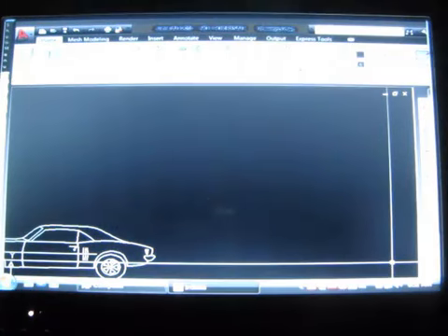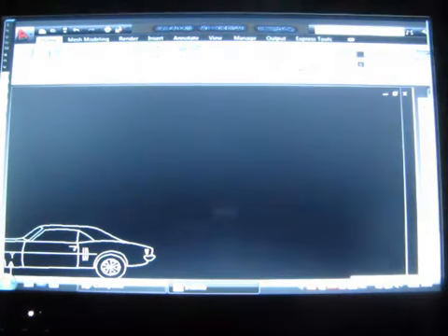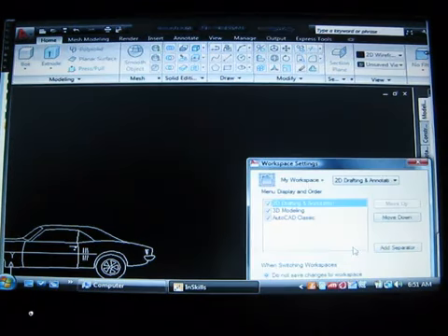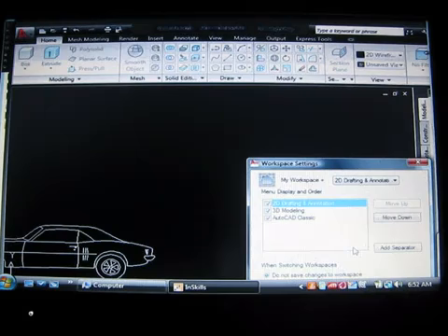There are some things you can do to manage your workspaces. You can do that again through the Workspace Settings button found here. Here you can arrange the way the available workspaces are displayed to you. You can even turn some of them off. If you make changes to your workspaces, you will need to save them. To do this, click the Automatically Save Changes option to save your workspace setting when you switch or turn off AutoCAD.